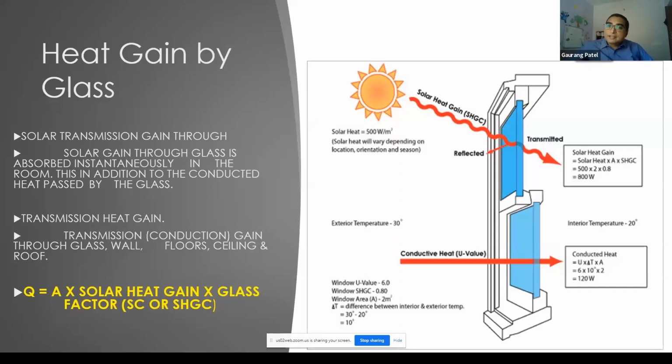Your glass has certain properties. Your home glass, which is very common, is 4 mm clear glass. But when you go to any high-rise or office building with a completely glass facade, you can see green or blue glass. If you look closely, it will be thicker glass, sometimes a single pane, sometimes a double pane. There is a variety of glasses available, and that has an impact on your shading coefficient. The glass provides what? Shading.